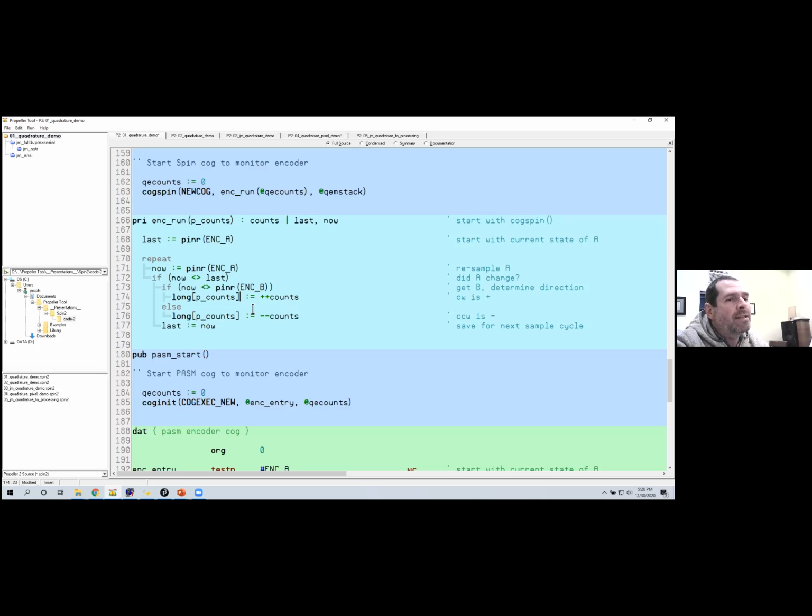So they, on reset, are configured. There's 4 different ones you can choose from. One is very high speed, and it goes all the way down to like 100 milliseconds at 160 megahertz clock rate. And what these things do is they vote. Like, it wants to see unanimity out of, I think, like 3, 5, or 8 bits, and it samples at different rates. So when everything reads 1, then your output changes to 1. When all those flops read 0, your output then goes to 0. Okay. So yeah. You could select one of those preset filters, and it would digitally filter for you, and that would probably be totally sufficient and maybe better than just a Schmitt trigger.